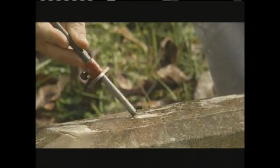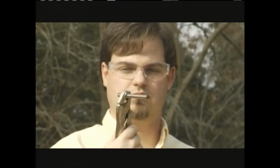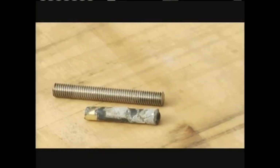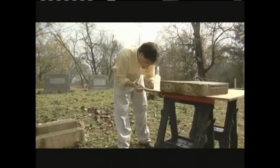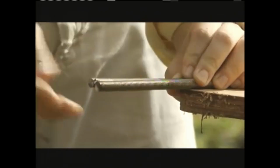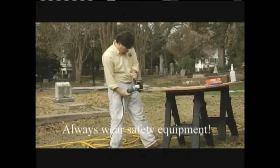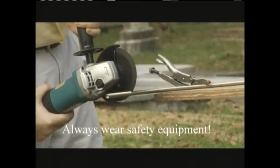Now we will insert new pins made out of stainless steel all-thread. Stainless steel will not corrode over time the way bronze and steel pins will. You want to make sure that your new pins are just slightly shorter and smaller than the holes. This helps eliminate movement due to expansion and contraction over time.